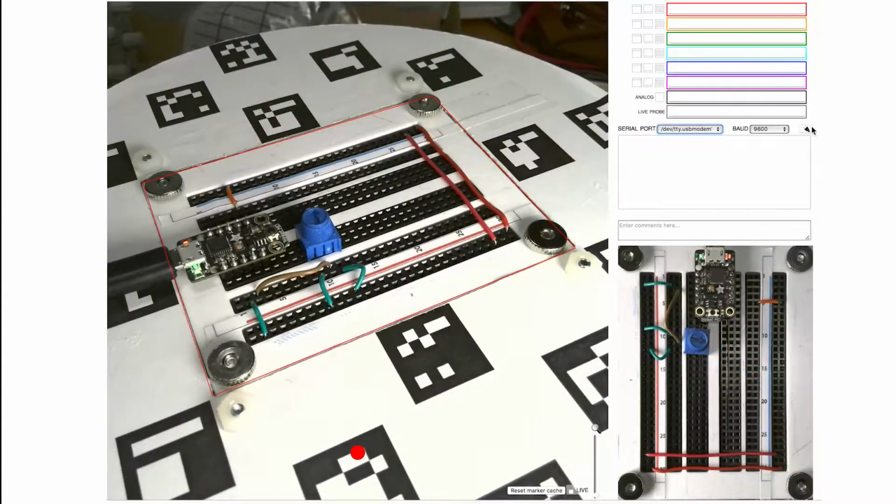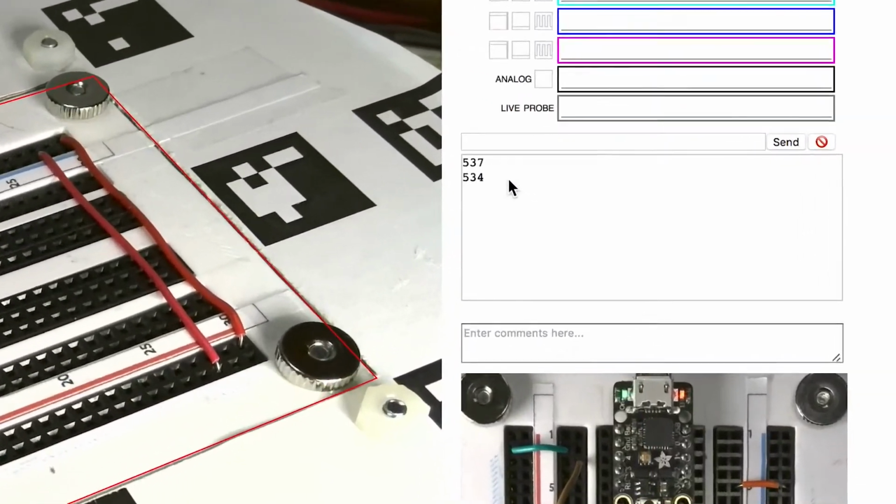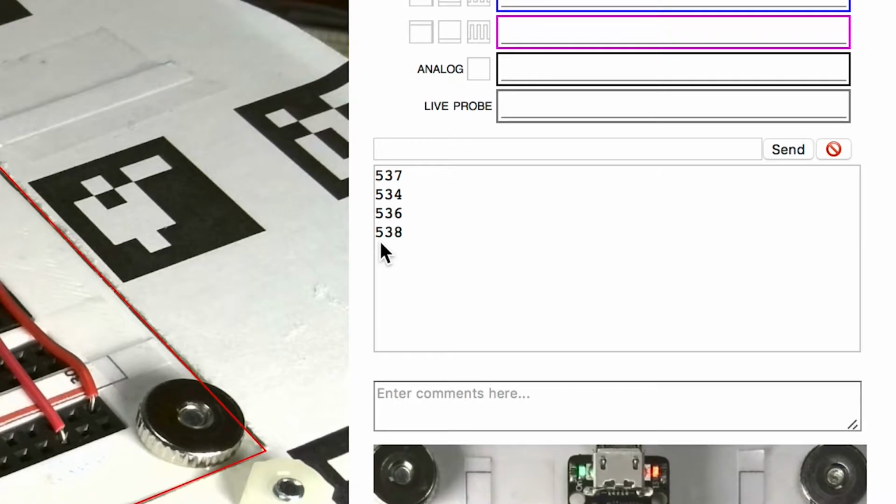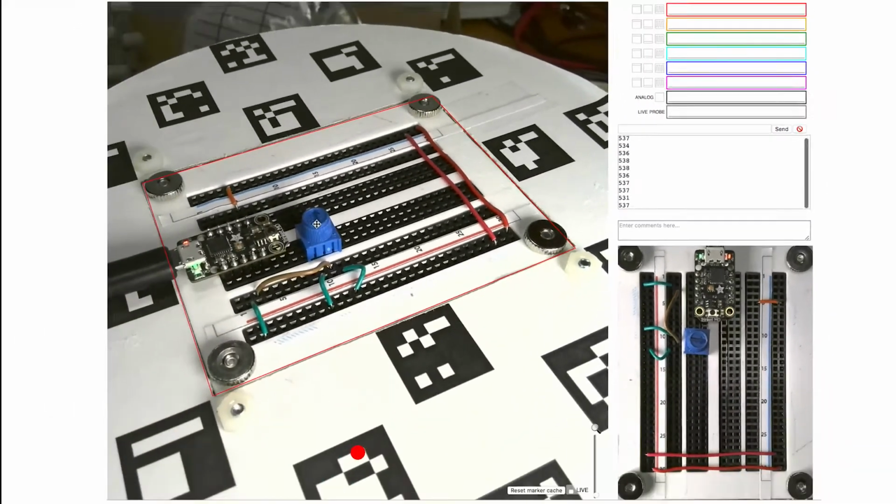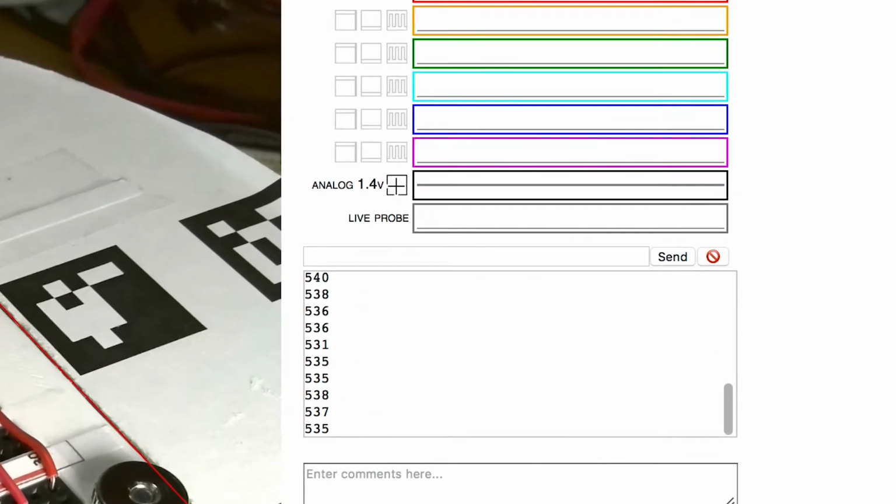In this next example, the student is printing the analog input of a potentiometer to the serial console. We see the serial messages live and can understand the inner workings of the microcontroller with it. To simulate the potentiometer being adjusted, we can dynamically inject an analog voltage into the input pin of the microcontroller. We now see the serial output of the student microcontroller being changed by the debugger's input.